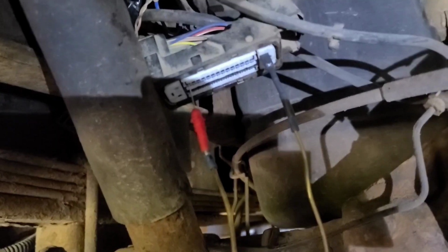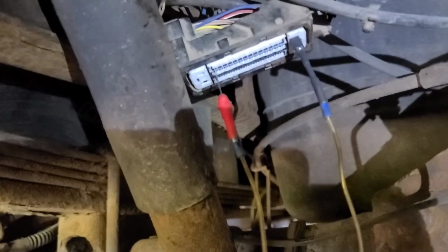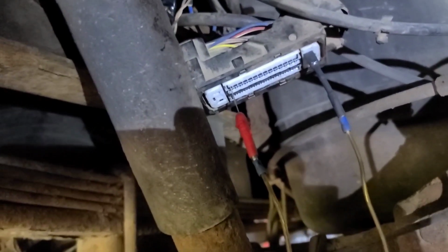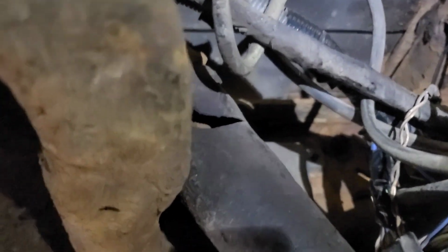This is rusty. So pin 15, which is at the other end of the row, pin 1 is on the ground, is ignition feed from a 15 amp fuse, and it lights a headlight. So that circuit is good too. But in the wiring diagram, it shows a trailer brake relay. And I don't see it.